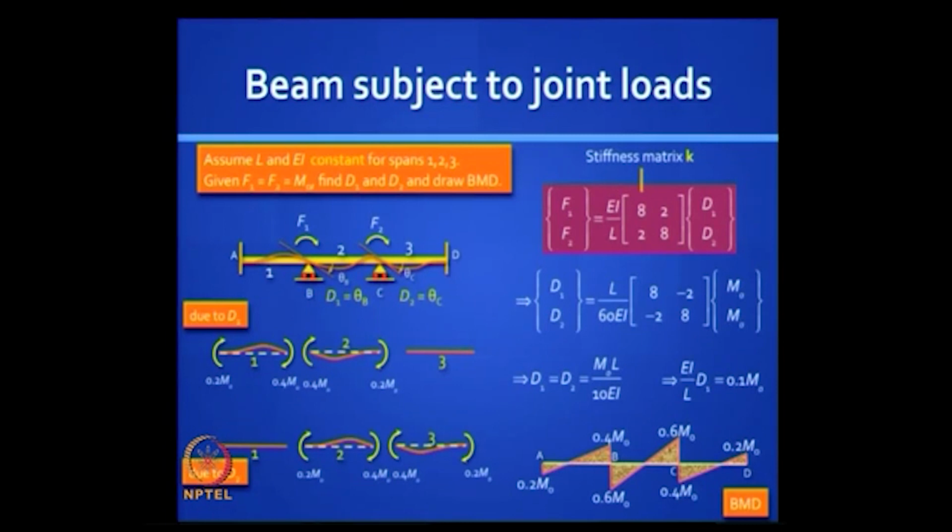So we did this from first principles. And look at the deflected shape, it is more or less showing the right thing. You get hogging in some region, you get sagging in some other region, there is a point of contraflexure. Does it make sense? So we did something from a completely different perspective, a fundamental approach. Is it clear?